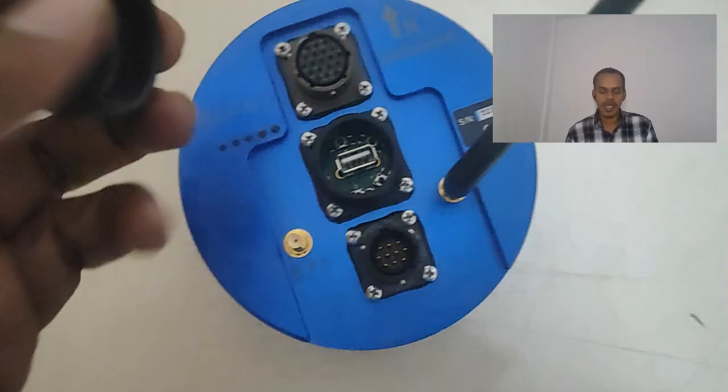In most short-time surveys, or where you have some seismic microzonation, people don't go for online servers. They directly take this digitizer and keep it on the ground on a level surface, and then they collect the data, which is stored in a pen drive and taken for processing.